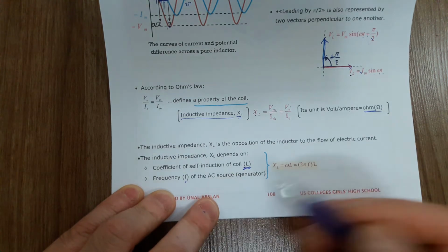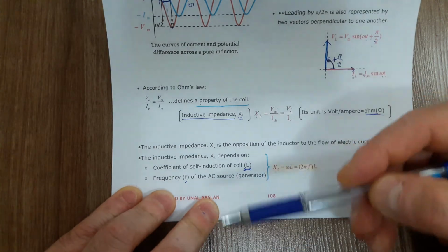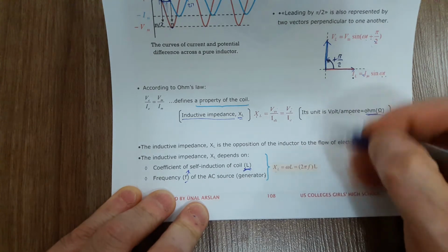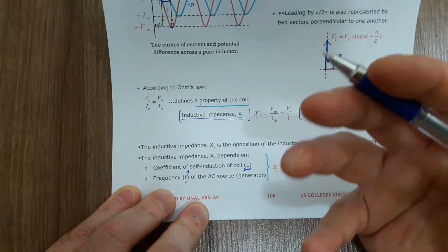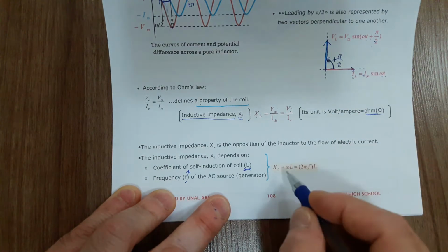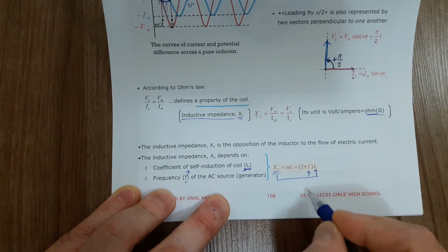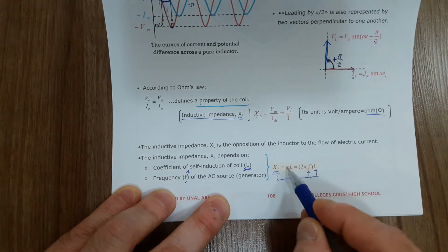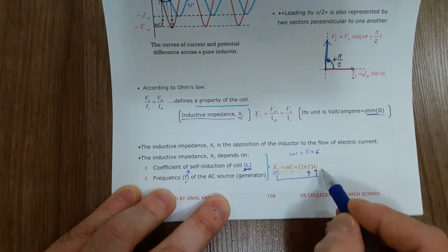Why does frequency directly proportionally change the XL? Because the coil resists the change in the electric current. If you increase F, which means you are making a change at a greater rate, then the coil will resist more, so the opposition of the coil to the electric current will increase. That's why XL is directly proportional to both L and F. So 2 pi f L is the equation for calculating XL. Sometimes 2 pi f is not given, only omega is given, because we can also write 2 pi f as omega. Omega L, or 2 pi f L, is the equation for calculating inductive impedance.